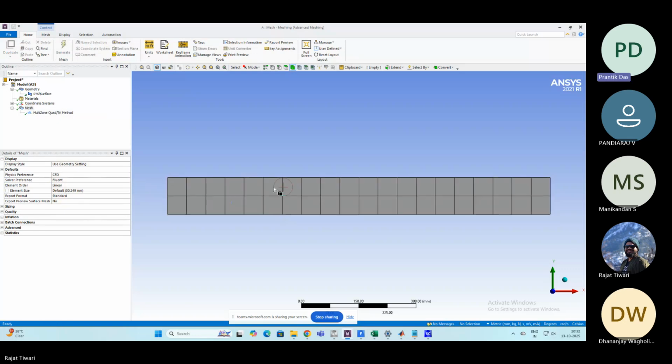So now you can see that the whole domain is divided into these control volumes. So I've actually made you learn in the class how to solve the 2D problem, a purely convective problem, by using the upwind scheme. So that was not a coupled one. It was like a general transport equation, del dot rho v phi equal to 0. But this one, we are solving the continuity and the momentum equation in a coupled manner.